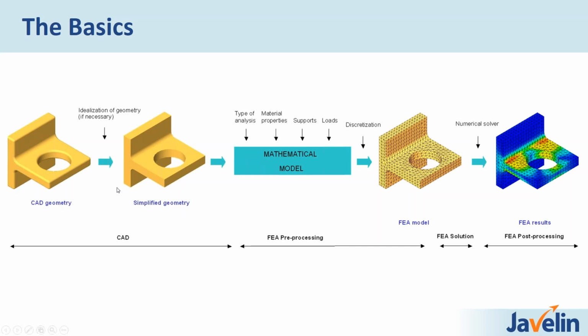They're not really going to affect the stress result, but they will be very hard to mesh and control the stress around. So, tiny little features, get them out. Then we'll start with the actual setup of the model, and this is what we call pre-processing, sort of everything before we hit the solve button.